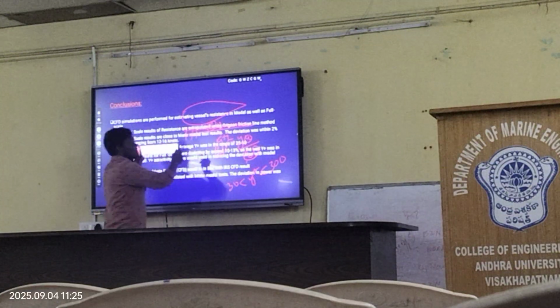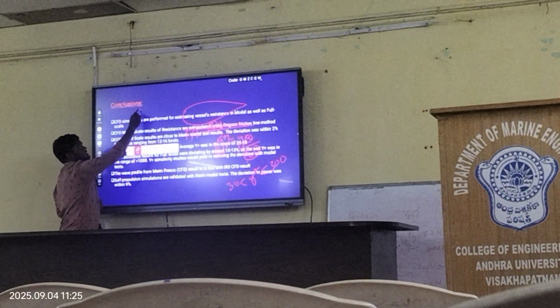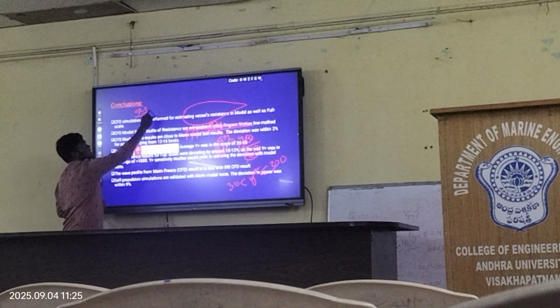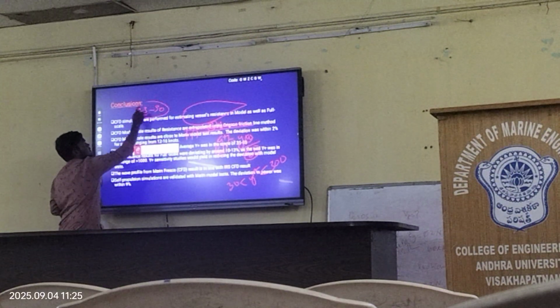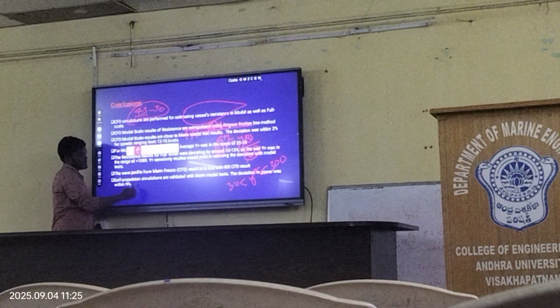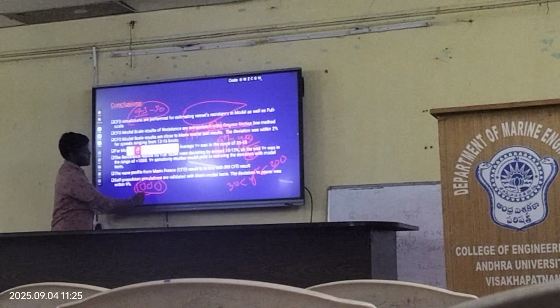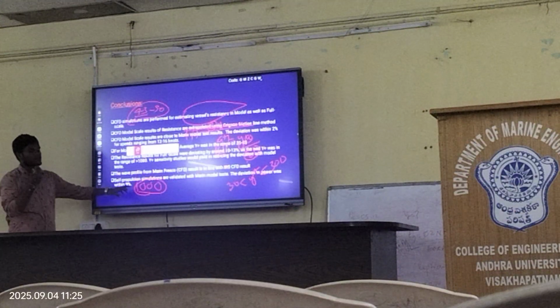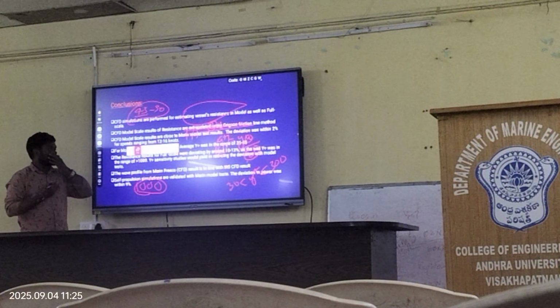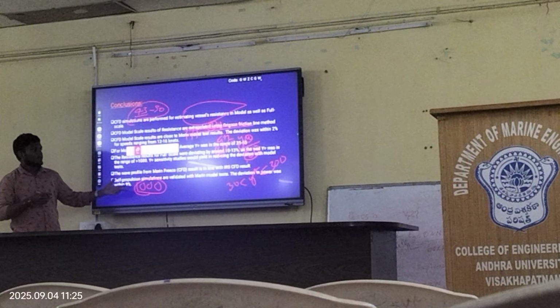As I have said, for the model scale, I obtained a y plus of 43 to 50. But in the case of full scale resistance, I obtained it in the thousands. I have researched this and come to the conclusion that there is some error with the model.